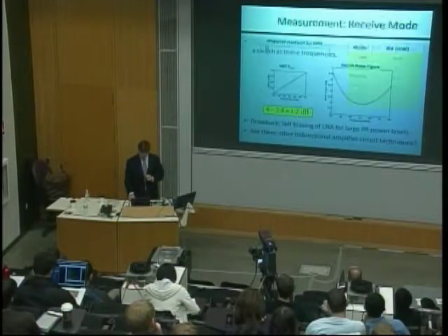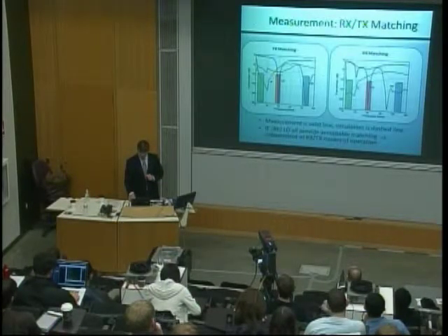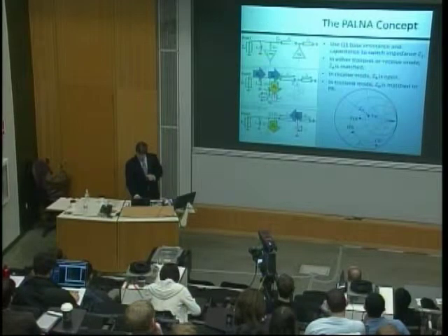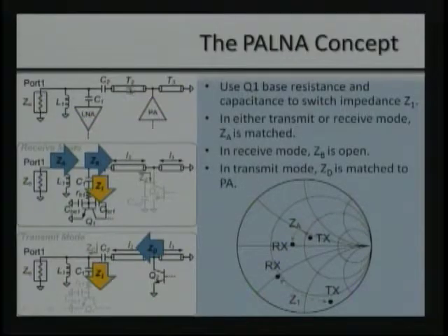And if we go back and we look at the circuit, it's pretty obvious where it was. This PA basically is transmitting all its power across the input of the LNA. So if you try to transmit too much power, the transistor acts as a rectifier, right? Which means that the swing will essentially turn on the transistor. So there is a limit to how well this approach works when you try to transmit very high power levels. In our case, 10 dBm doesn't turn on this device, but at higher power levels, you can get a feedback through that turns on the LNA and then feeds back through the PA.